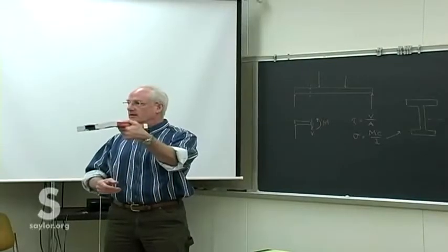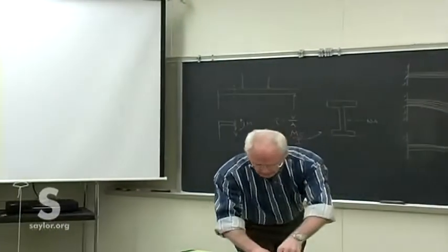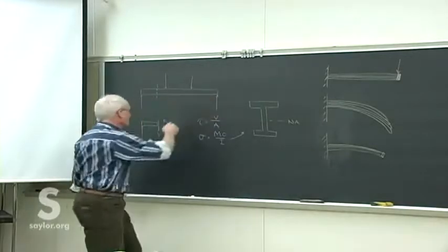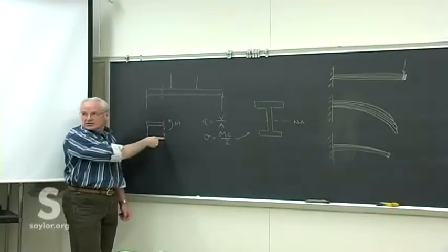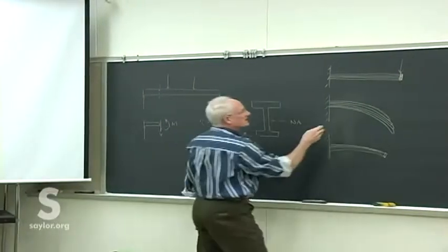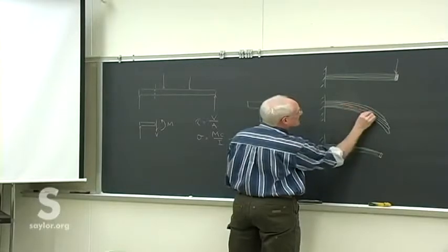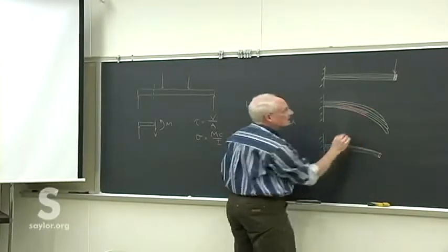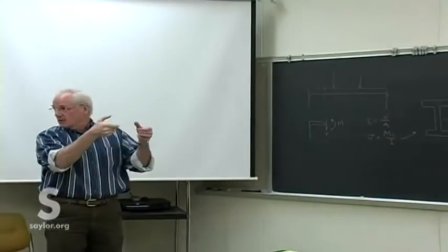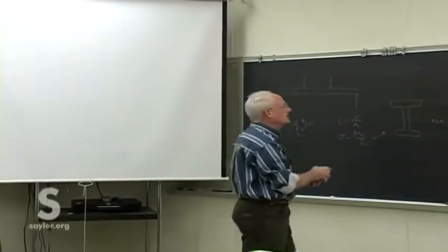It does even better. So what we see is that those loads, like these and like these, that cause cross-sectional transverse shear also give us some kind of trouble that we need to address of this longitudinal shear along there. We need to address how to keep the fibers of the beam, and it's especially true with a wood beam that is truly made of fibers.